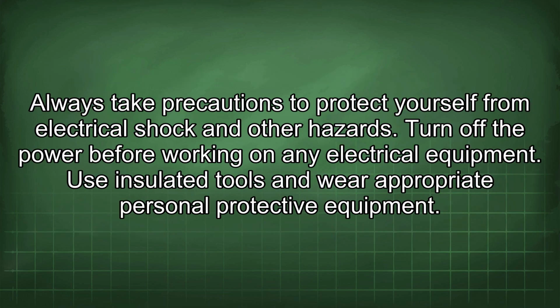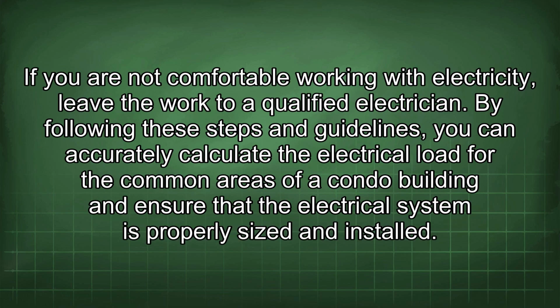Always take precautions to protect yourself from electrical shock and other hazards. Turn off the power before working on any electrical equipment. Use insulated tools and wear appropriate personal protective equipment. If you are not comfortable working with electricity, leave the work to a qualified electrician.